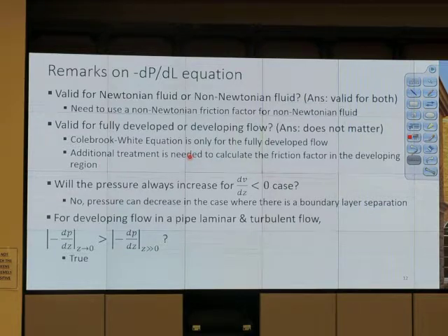So this means if I turn on the pump and have it move slowly, maybe it's not that viscous. But if I have a very high pump speed, let's say I use a centrifugal pump, it breaks the droplets, it breaks everything and mixes together. It is more viscous that way. Okay? So emulsion can be shear thickening in some sense.